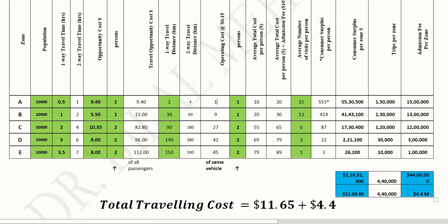we go ahead. This is for various regions, and it is also increasing as we go from region A to region E, because the greater the distance, the greater will be the value of the operating costs. You can also see the calculation, that is 4 into 0.15, because 4 is the kilometer distance, two-way travel, and per kilometer operating cost is here.